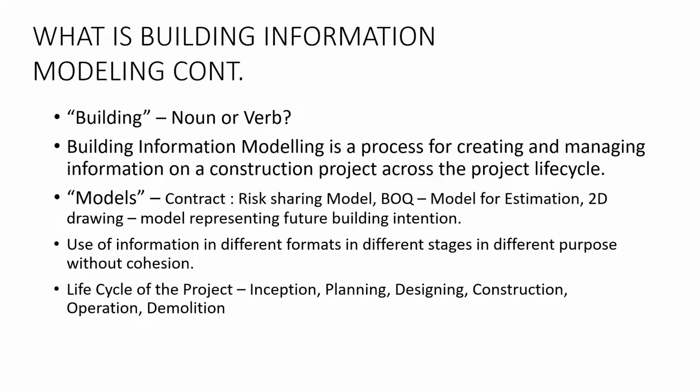So as an example, in this BIM execution plan, we have to identify the function of the construction. Let's say preparation of detailed design. For preparation of detailed design, we can use Revit software, and after that we have to define the people who are involved for that particular task. So we can assign draftsmen and architects for that function with this Revit software, and then we have to think about the purpose of using this building information modeling technology instead of the traditional method. Of course we can increase the design efficiency, accuracy, and with the 3D visualization, we can easily explain to our clients about the design changes. So that is the purpose of using this building information modeling in that stage.